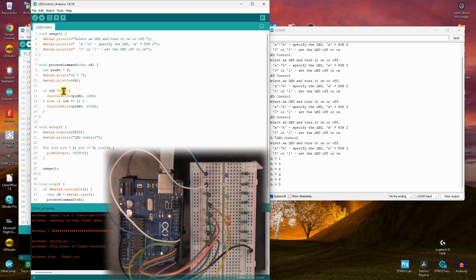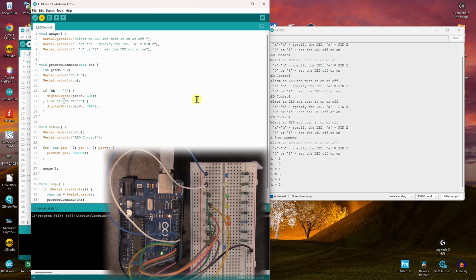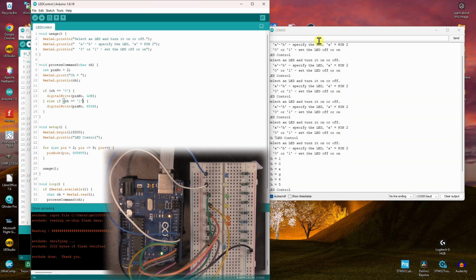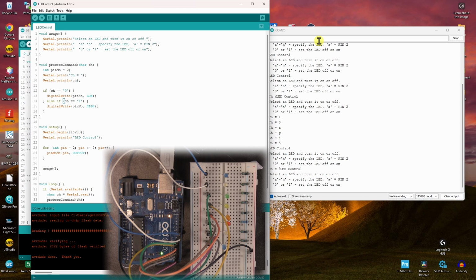And that's not a 30 or 31 hexadecimal. It is, in fact, a character 0. So hopefully you remembered that, but I did that deliberately to remind you that even though we're typing numbers in up here, they're not actually numbers, they are characters. You don't get a number through the serial monitor. Again, there's support where you can get numbers out of it. Look at that a bit later. Well, actually, we won't look at that later because it's problematic, but it's just a reminder of how it works.